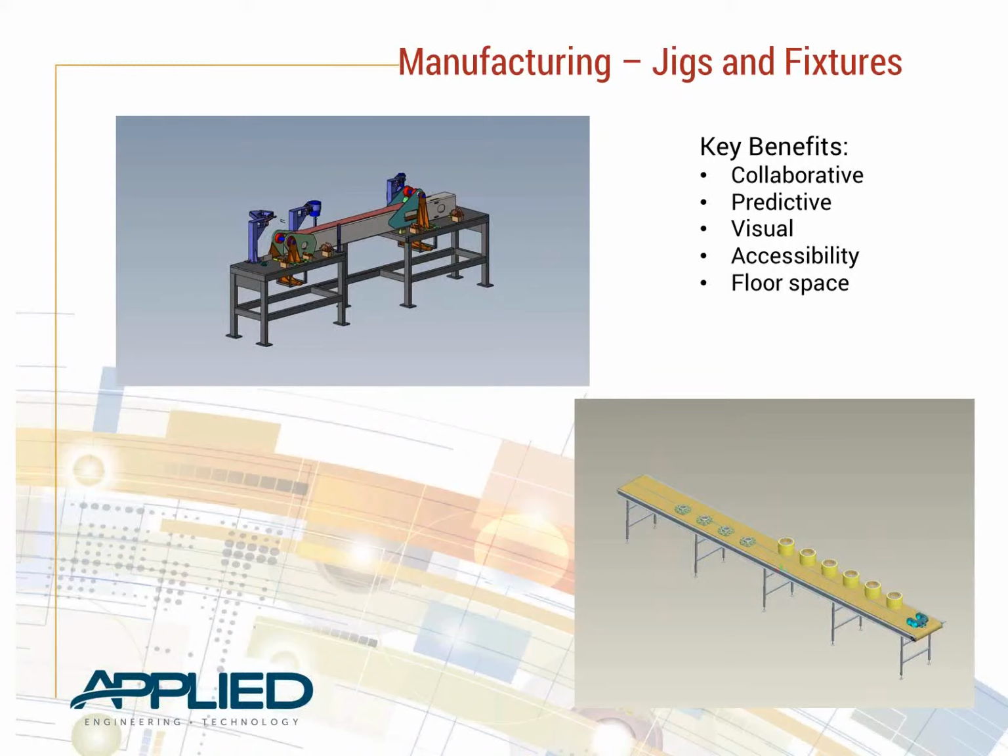One project I can think of in particular is where you take the CAD model directly and build it just like you would in a sandbox or at the workshop, your normal fixture, but you do it digitally. What that allows you to do is make sure that you have access to get into parts where you need to do assembly. So you can spin it around and ask, I'm going to put this bolt in, am I going to have access to get that? You can visually see what's going on there.